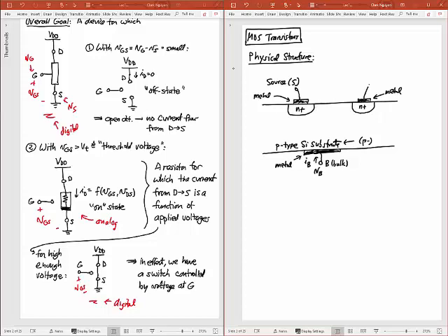And show its terminal there. This is now what's called the drain. All right, so I have a source of electrons, and like water, I'm going to drain them at the other end. I'm going to collect them at the other end. That's what this other N plus junction is. And so between the two of these, I have my gate. So my method for controlling how much current will flow.